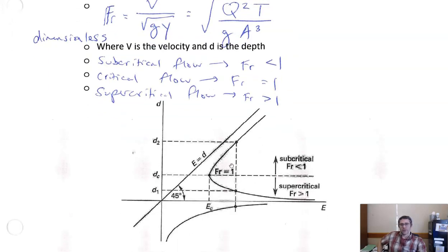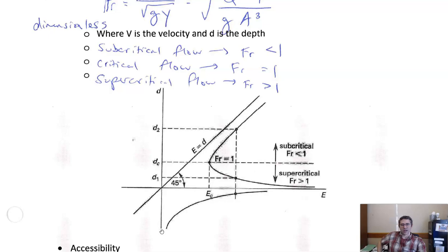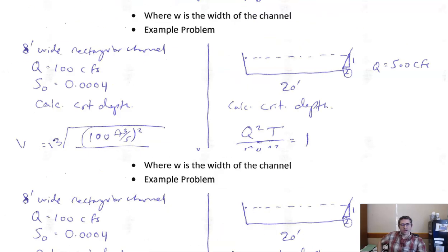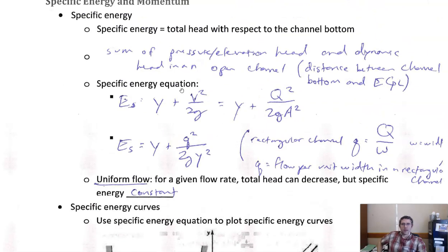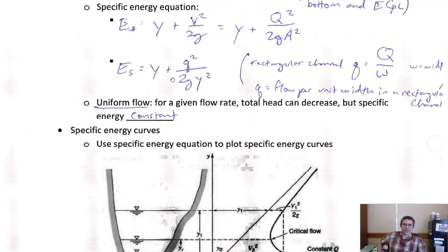This diagram too, I just wanted to highlight one other thing. So we've got the Froude number ranges shown on here. And you see this thing down here too, right? This is plotted at a negative depth. And this is going to be important to recognize that this thing exists, because it turns out, going all the way back to the beginning, this thing, while it looks like it would just plot like this, it's actually kind of like a cubic relationship, because y is showing up here and in here.